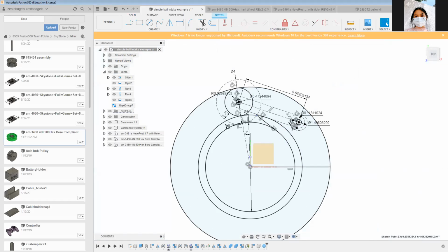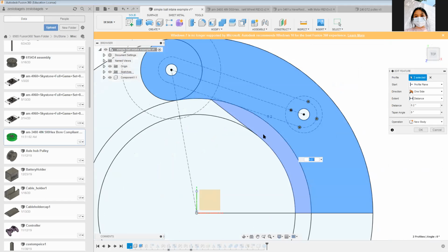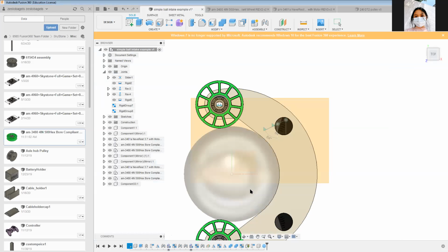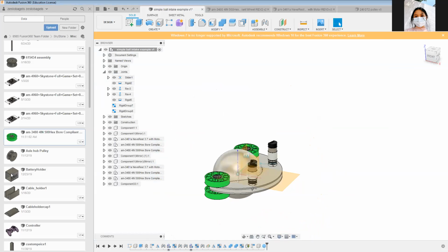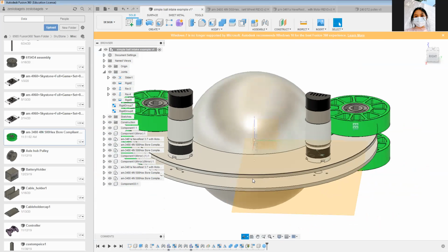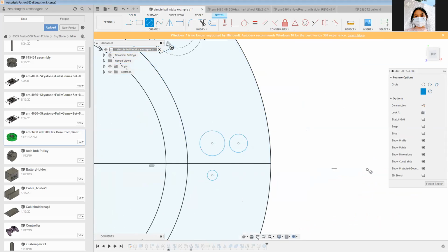And now if we edit the first extrude, we can add this to it. And now it's a good intake. And then if you wanted to put mounting holes on here, or to make this more 3D, you just add more sketches in different dimensions with all the parts you need. Like you could add holes here for mounting or something.